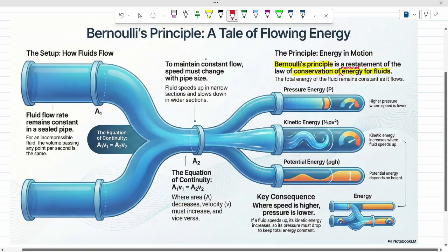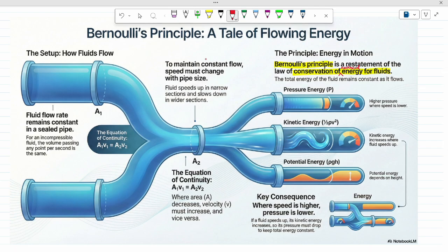But let me just briefly mention, when you have a fluid that's flowing, then different things can change. As fluid flows, for example, the cross-sectional area of where it's flowing might change. Now, in those contexts, a lot of times you would keep the fluid flow rate constant, or you might just be more interested in keeping how many gallons per second the same. In those cases, the narrower pipe forces the fluid to actually flow faster. That's what this equation of continuity expresses.